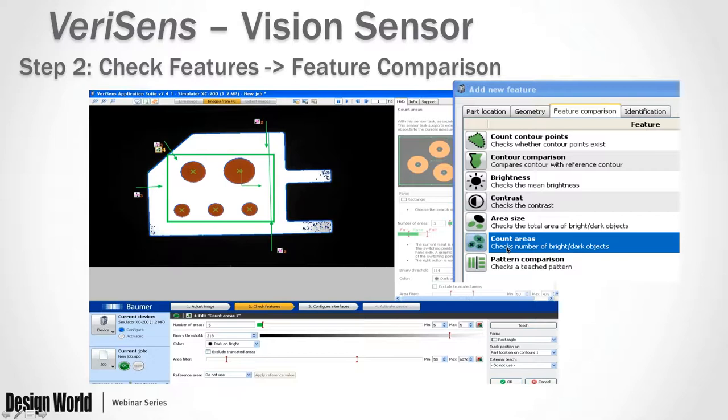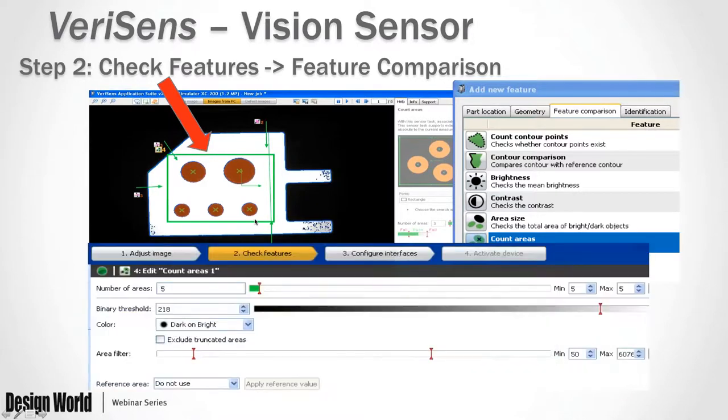We're going to look for a certain number of blobs, and these blobs will consist of a certain amount of pixels that are all typically about a similar grayscale value. So these were all dark back here, versus its front side here. And we draw that tool across there. We're actually going to drag and drop that box that's here. And once we do so, I'm going to have it automatically come up and tell us that, hey, we have 5 blobs or 5 areas that we've detected.